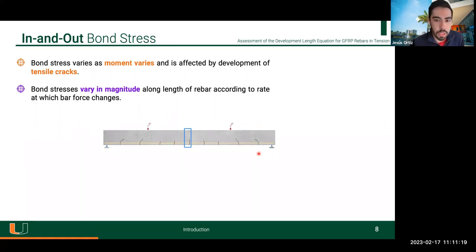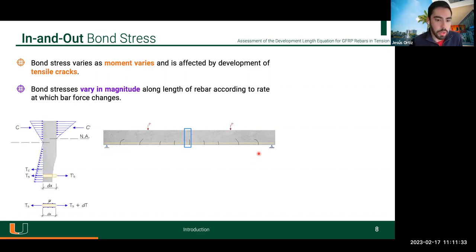So if we imagine that we have this concrete beam, simply supported, already cracked, and we make a cut on a cracked section next to an uncracked section. If we have a cracked beam subjected to this stress diagram, in the uncracked section the concrete is taking some of the tensile stresses, but of course, in the cracked section you have already lost that tensile capacity of the concrete.